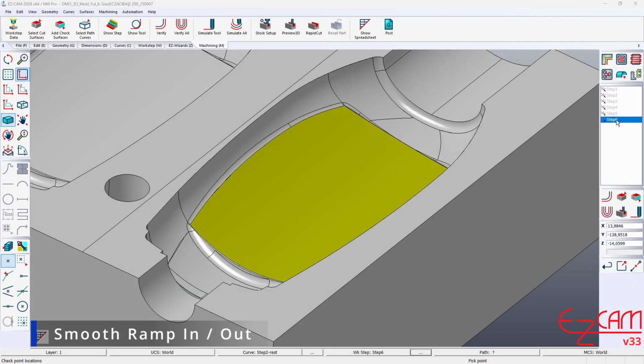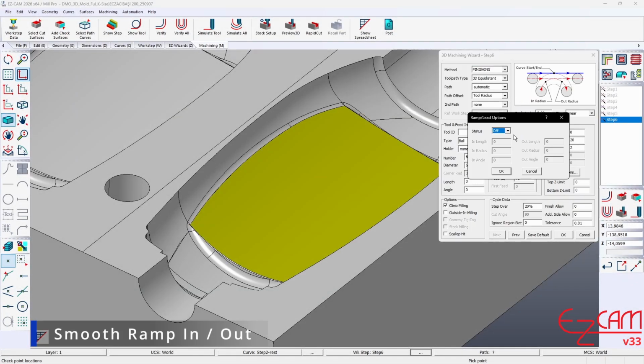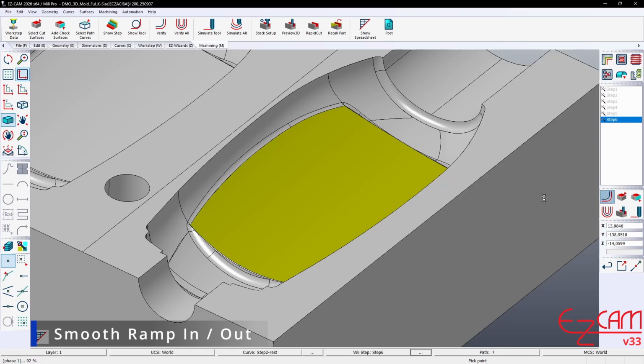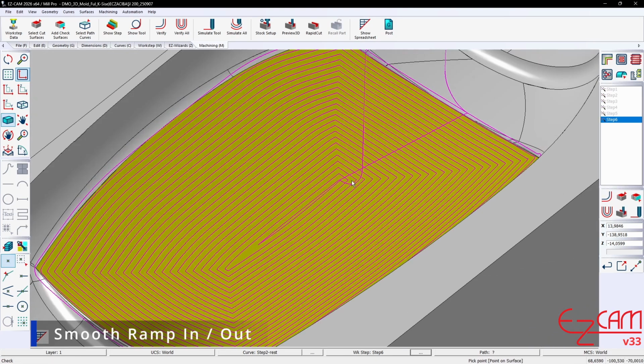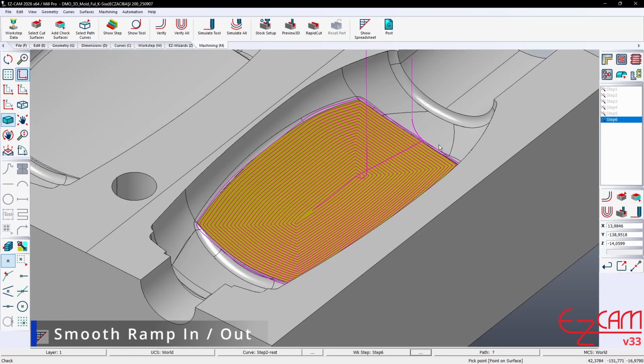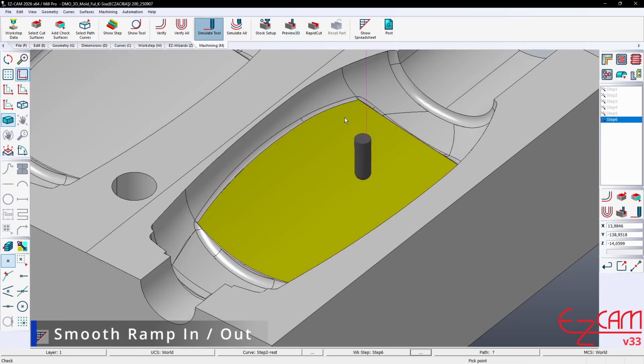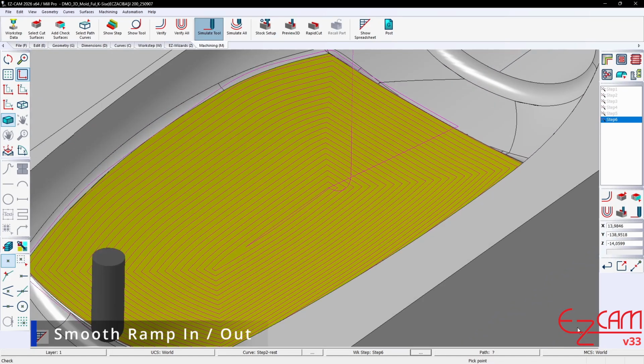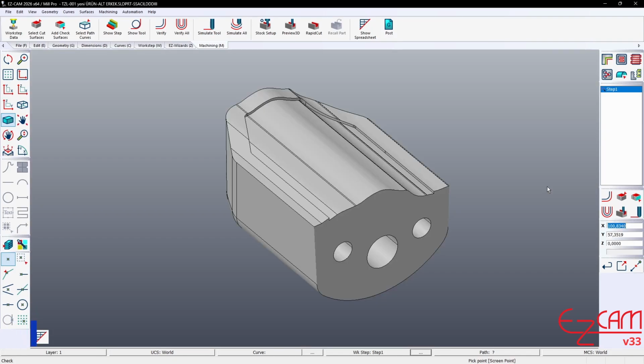Radius lead-in. There are also innovations regarding how the tool enters the material. Radius lead-ins allow the tool to engage the material more softly and in a controlled way. Sudden loads and wear are prevented, extending tool life. Because cutting begins in a balanced manner, surface quality increases. This method offers big advantages in machining hard materials and in high-precision finishes.